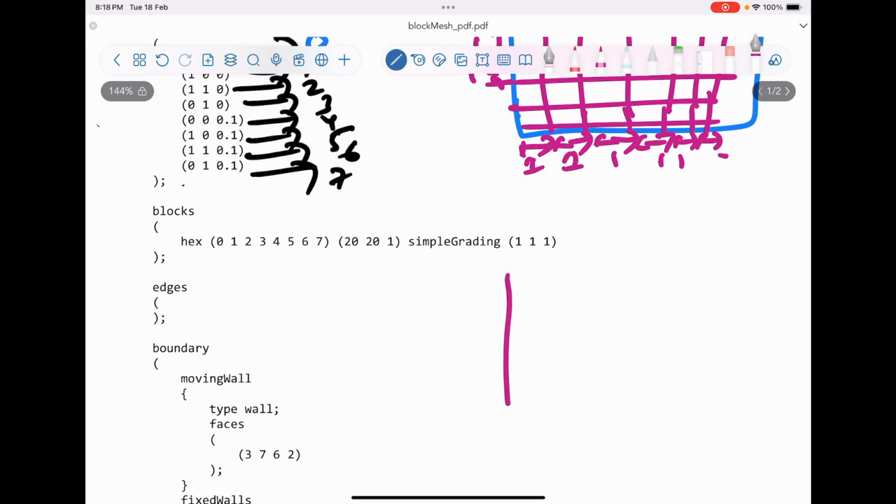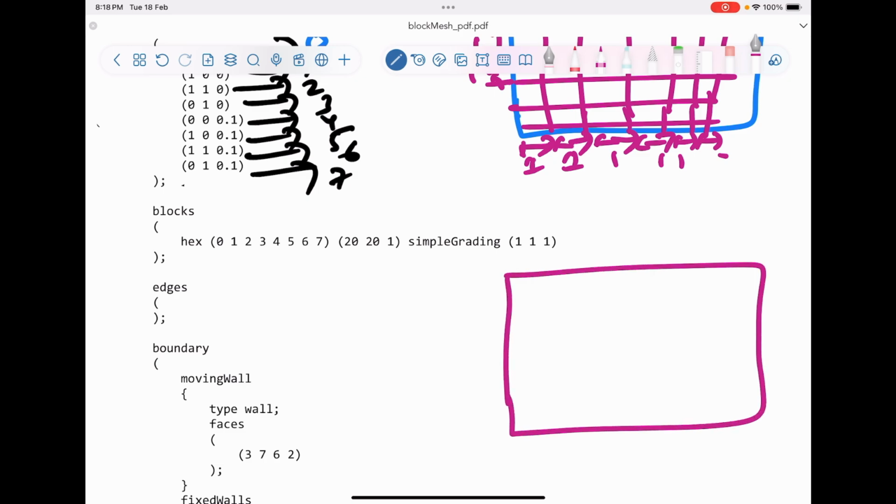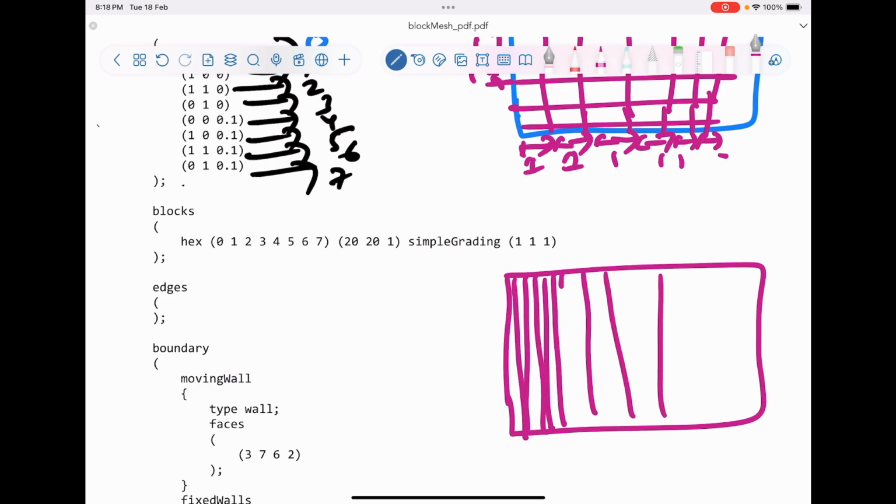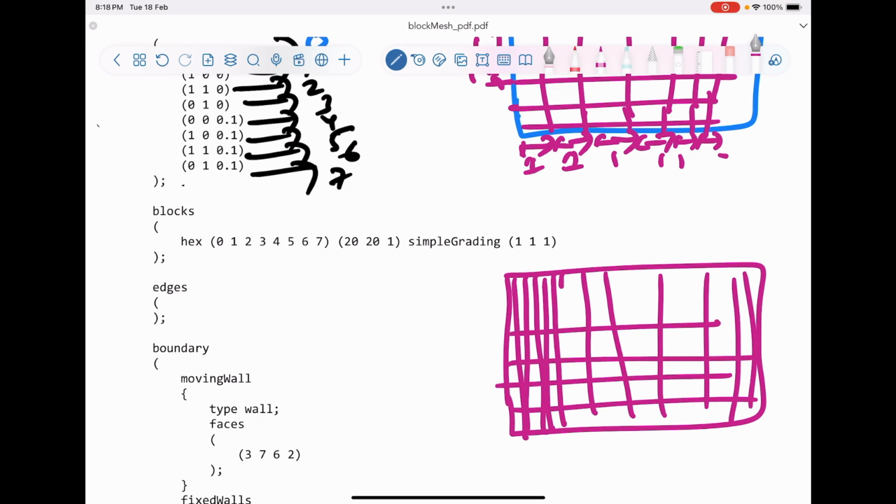What you want to do is make the mesh very fine first, and then it keeps increasing in the x direction, while in y you keep it the same. So what you can do is give a value greater than 1. This is like x, y and z only.